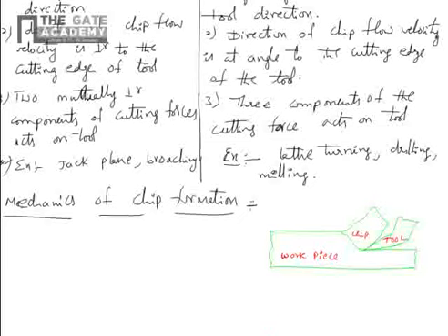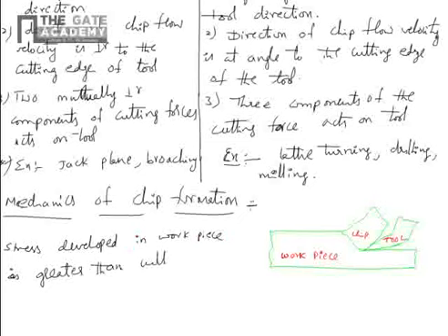When the forces applied by the tip of the tool on a layer of the material are such that the stress induced in the layer is greater than the ultimate shear stress of the workpiece, breaking takes place.